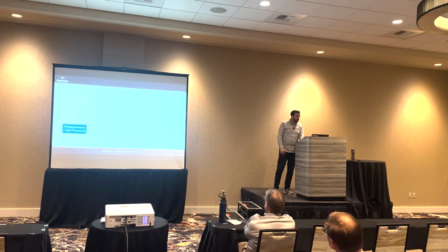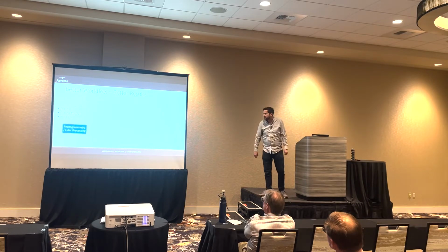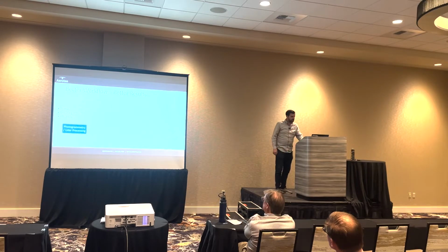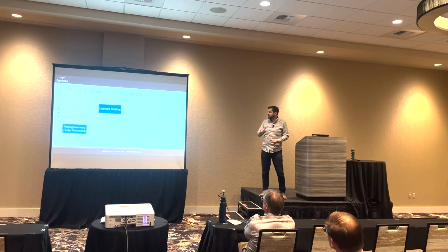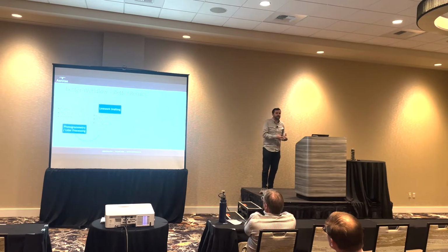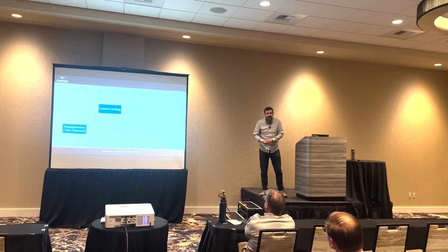An example photogrammetry workflow means that you start with your photos, your ground control data, your RTK and PPK. You process that through your photogrammetry and LiDAR processing system. That creates those rich deliverables. I call them rich deliverables because they're very large files, with enormous amounts of detail, more than you need. Things like your ortho photos, your digital surface models, and your point clouds. Typically, these are all what we consider intermediate deliverables, right? Each one of those is going to be many gigabytes in size for bigger projects, and is going to need a lot more work before you can deliver it to a client, before you can even open it in